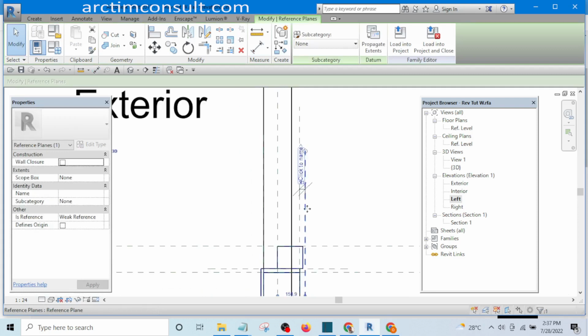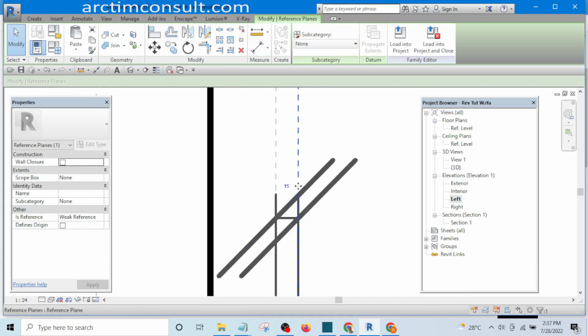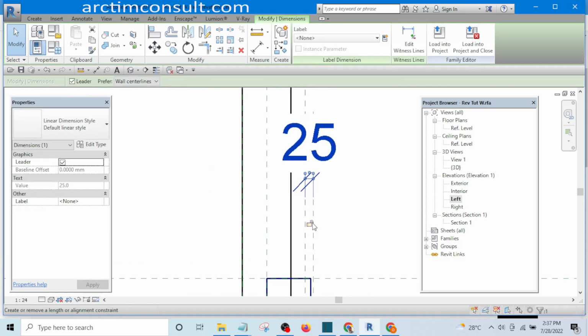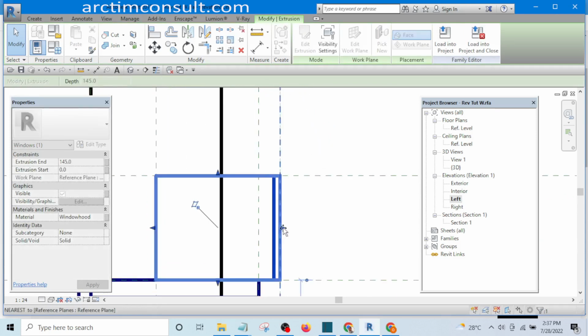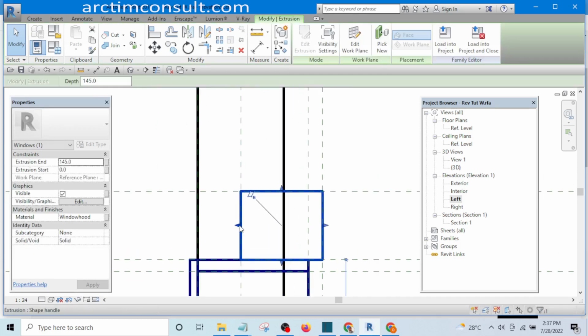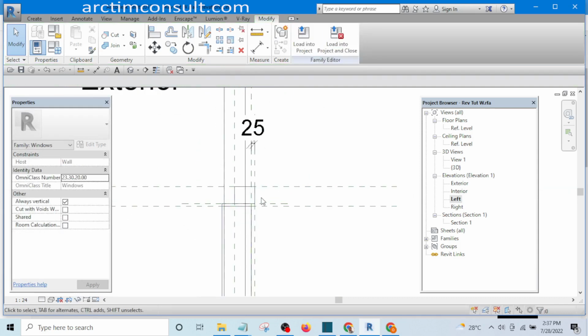And if this is about 1 inch, that is 25 mm. 25, and press enter. Then constrain it and stretch this one to here and constrain it. Then you can also stretch this to here and constrain it so that it will be intact at any point in time.